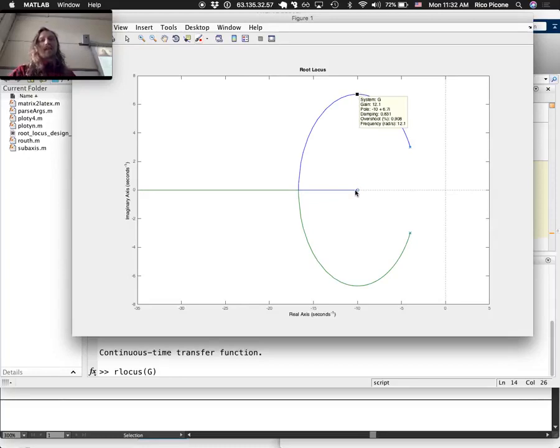Technically, we could be here too. It just works if we put it down here. What happens though? What would that correspond to? Well, you can read it right off here. It's right on the 0, so that's when the gain goes to infinity. So we could also get that transient response requirement if we turn the gain to infinity.